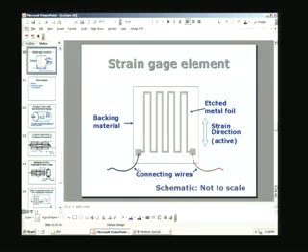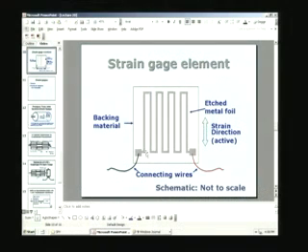A strain gauge element. I said just a little while ago that we can measure the displacement using a strain gauge element. What is the strain gauge element? It consists of an electrical conductor, or it could also be a semiconductor. Nowadays, semiconductors are also used because they are much more sensitive than metal elements, and it is arranged in this form, what is shown here. Several lengths are going to, in this case you have a long length of wire twisted around like this,